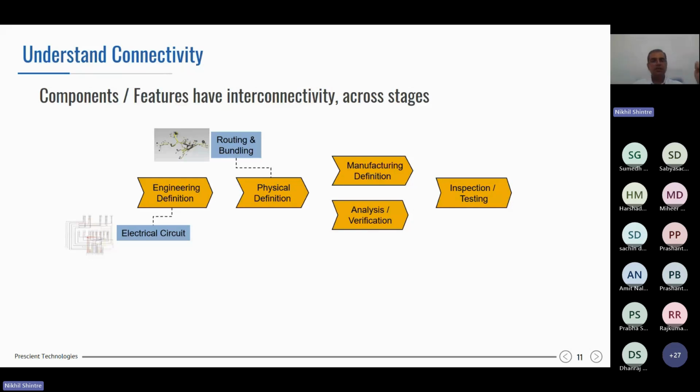So that is your second stage. The third, when it comes to manufacturing, you need to figure out the form board with which those wires would be assembled and that harness would be created. So that form board mounting needs to be defined, and that again depends on certain earlier steps.